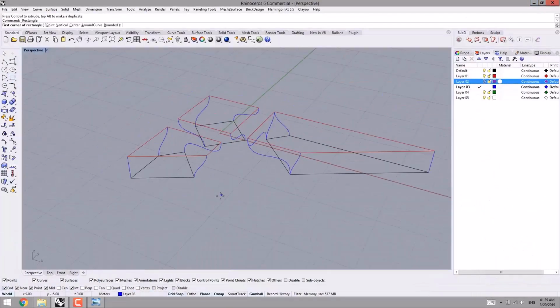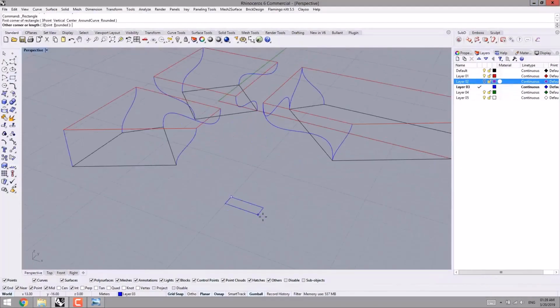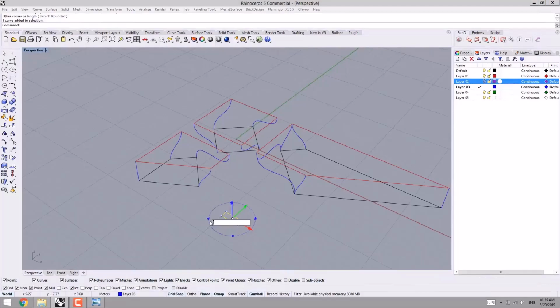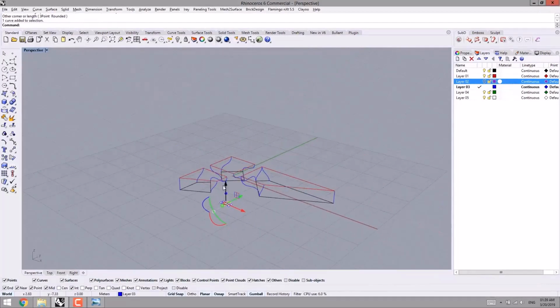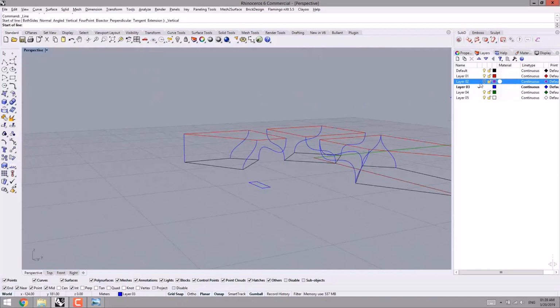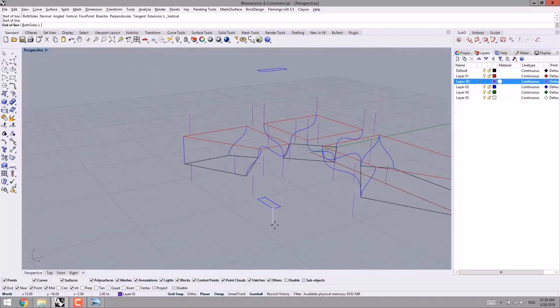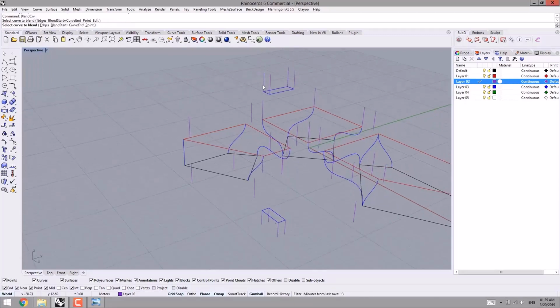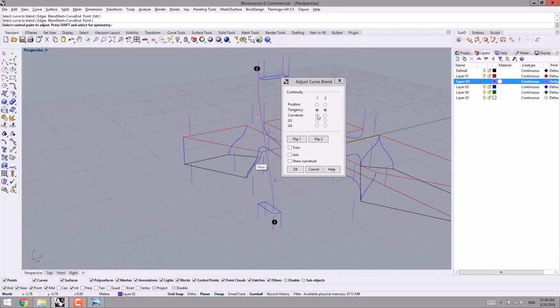and also in the final stage I wanna create or sketch the column. Here we can sketch a rectangle, for instance like this. I hold down Alt, 90 degrees rotation, and then I position it at this height. Again, I pick the vertical line by this way, layer 2, vertical line, then I make some copies to consider them as auxiliary lines, and then by using the blend curve command, I start it and then blend the curves.